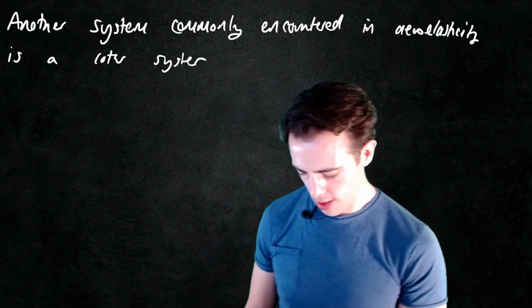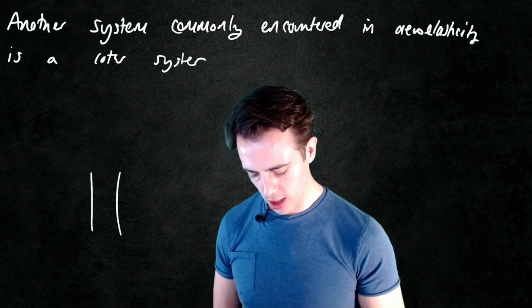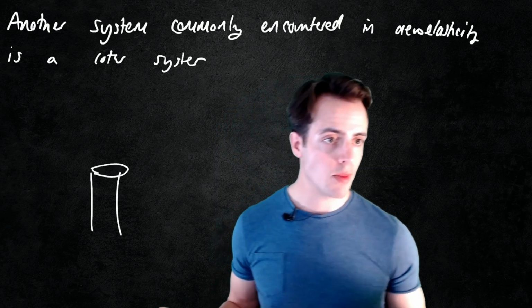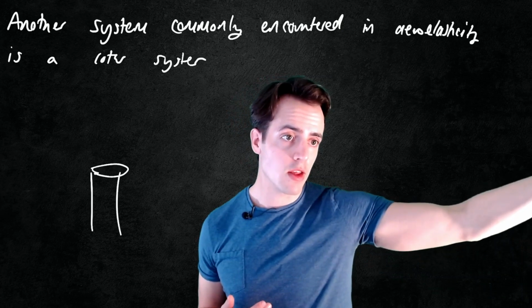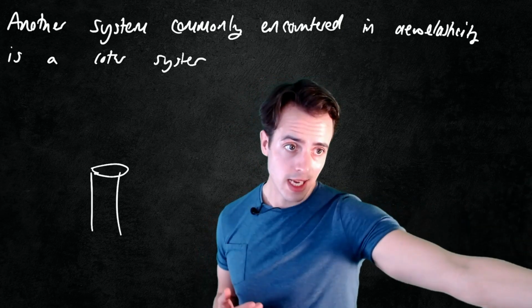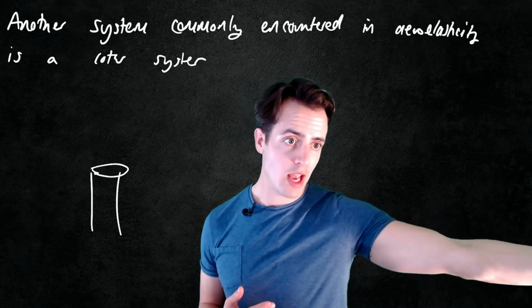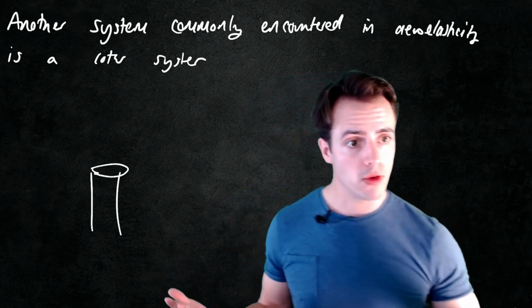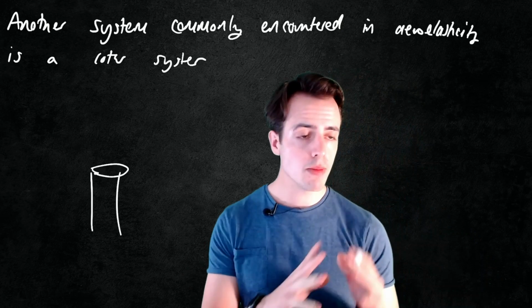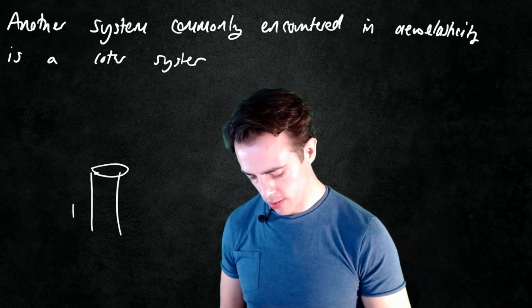I don't know how familiar you guys are with helicopter hubs, but helicopter blades are able to flap, which means they are able to have an out-of-plane hinge. They've got an in-plane hinge called a lead lag, and then they've got a pitch or a feather hinge, which enables you to change the angle of the blade. Those are related to blade dynamics, but they mean that we've got this system that's doing all these complicated things.